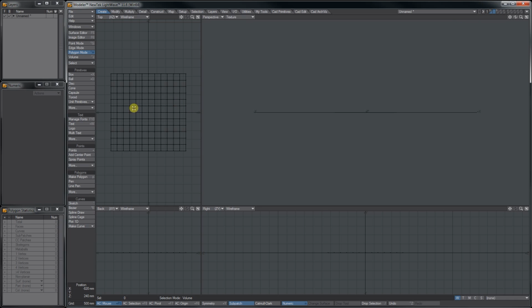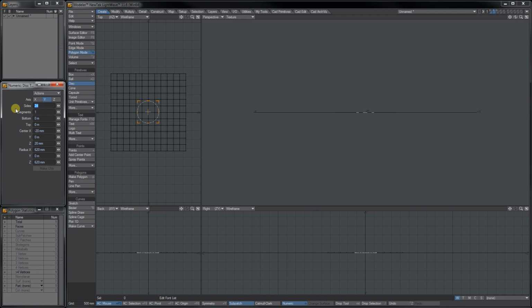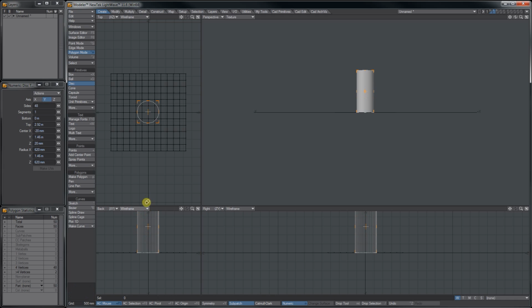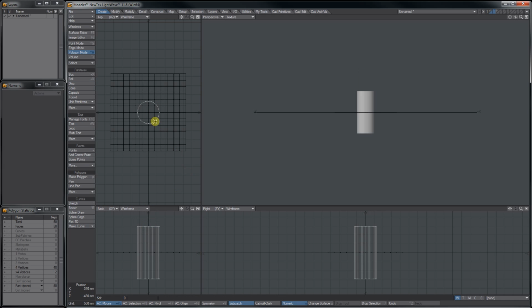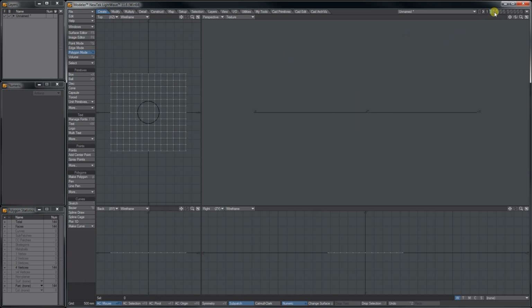Now putting the plane in the background and starting a new layer, I'm going to choose the disk tool, again holding the Control key to keep it circular, drag out. Now Richard set his sides pretty high to keep it smooth. I'm going to do the same here. Not sure how much it matters in this case. Then in the back view, drag it out just so I've got enough to go through my surface and through the curved surface later.